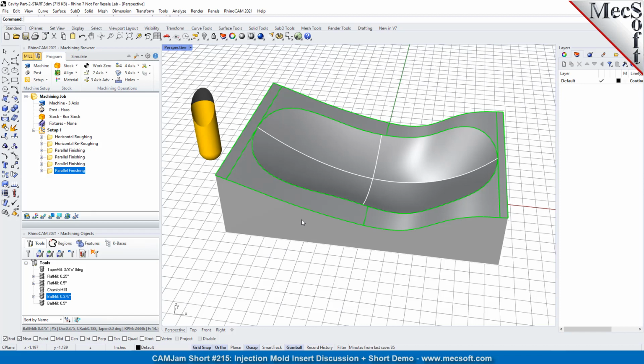If you refer back to our slide presentation, the first contact rule states that whenever the tool makes first contact with the parting line, that's it. It doesn't contact that point again. It doesn't roll on it. It doesn't do anything. It just contacts it and keeps on going. And that applies to both the cavity areas and the parting surface areas.